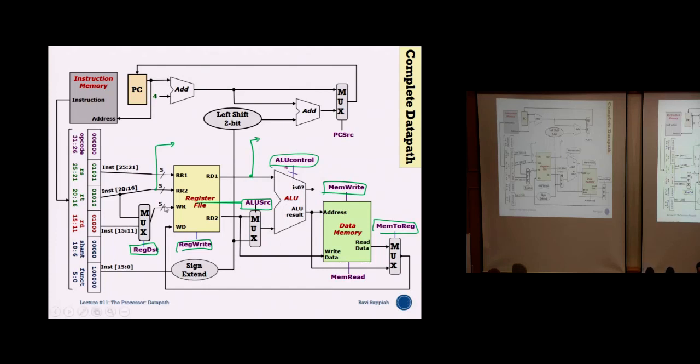This is set if S0 less than S1. So S0 less than S1, you want it to be set, right? So it will be 1, so it's not equal to S3. Okay, so it's fine. So I don't need to check individually for equal to 0. It's just like coding, there's no one way. As long as the logic is implemented, whether you check equal or check not equal, it's up to you.